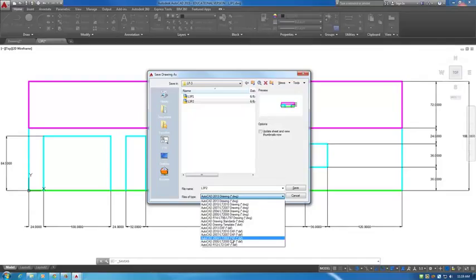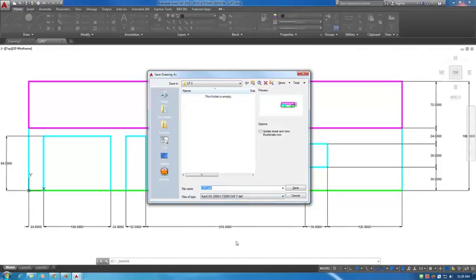exchangeable file extension. Generally, if you want to actually make a drawing and send it out to, say, a laser to cut, you're going to want to save that as a DXF. In my experience, because there is old equipment out there in industry, I tend to save it as an AutoCAD 2000 or LT2000 DXF, because that's the oldest version you can usually find, and it'll be more likely that older CAM software will open that up. So to save this as DXF, just simply click DXF and click Save.